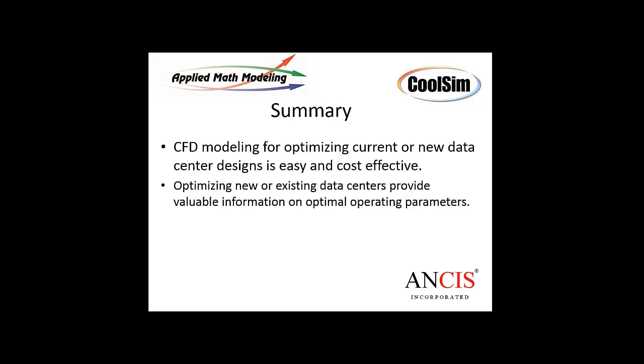The next thing I do, if I'm in a data center and I get a chance to look at it, I just stare at the rack and see how many servers are in it. If I know that the watts per rack is, let's say, 10, and there are 4 servers and they're in these slots, then I'll go in and put that detail in place. Easy enough to do in CoolSim. We make it very fast and easy for you to lay out where the wattage is in the rack. So I usually divide pretty evenly. You don't have to kill it in terms of detail to get good advice out of these systems.